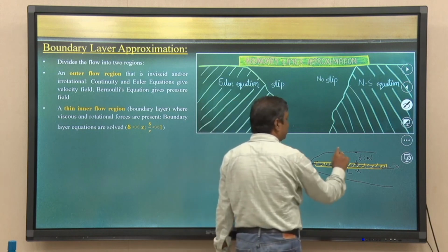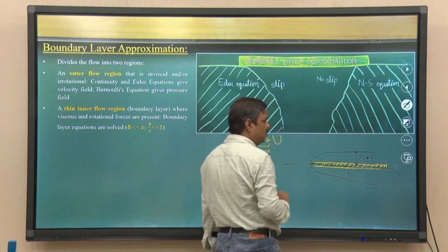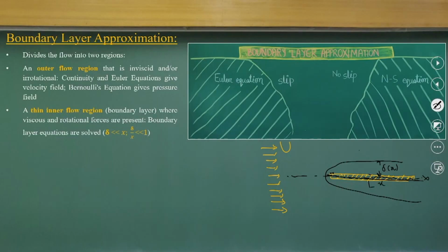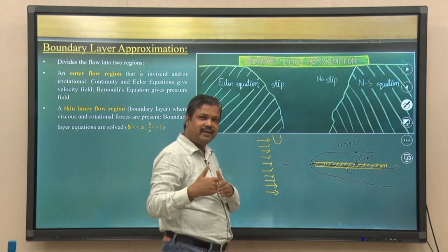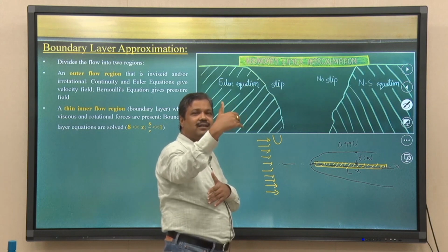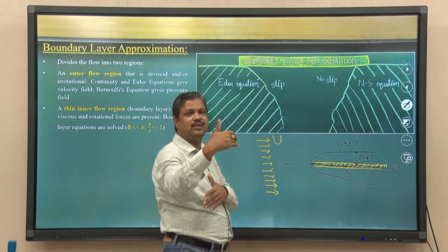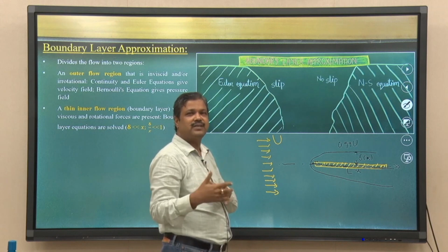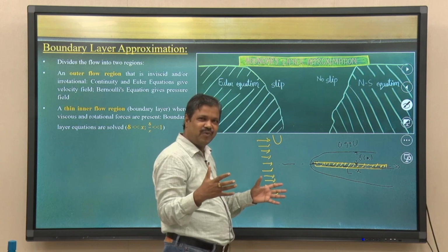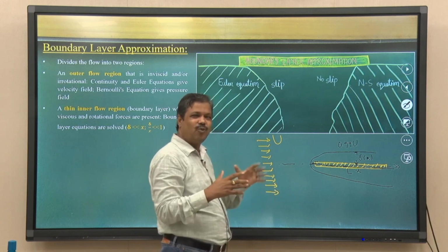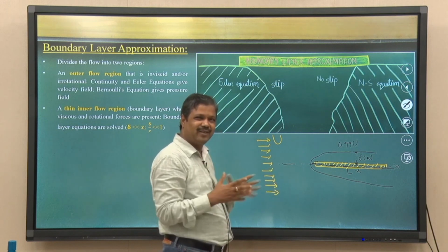We define the boundary layer thickness where, if U is the free stream velocity, the velocity reaches 99%, that is 0.99 U. One boundary is at the plate, and the other boundary is the point where the velocity is equal to 99% of the free stream velocity. This is hypothetical, but it is okay. 1% we consider okay, no problems.